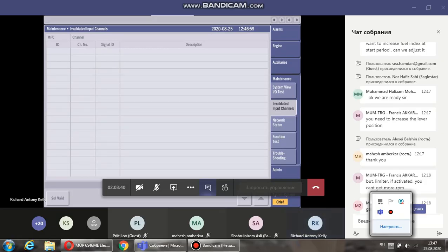The same with your exhaust valve. Of course, you would lose the monitoring of the position of your fuel plunger, but then you are also able to remove the slowdown, because the system has nothing to compare it to. So therefore, it doesn't think there is a problem, and it will continue to run. I wouldn't advise that unless you were certain of the situation, but that is what you can do.